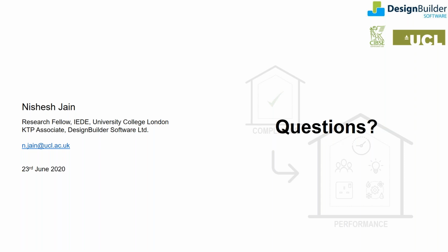Once you have a working model, which is a kind of baseline model for a design, in terms of calibrating it, yes, you can calibrate it based on your monthly bills, and that would give you a good indication. That will prepare a model for an existing building, and you could use lots of the assumptions which were there for that particular building type in your subsequent models.